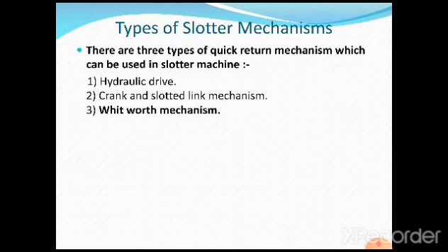These are the three mechanisms that can provide the cutting stroke slowly and the return stroke faster. That principle is adopted in all these drives: the hydraulic drive, the crank and slotted link mechanism, and the Whitworth quick return motion mechanism.